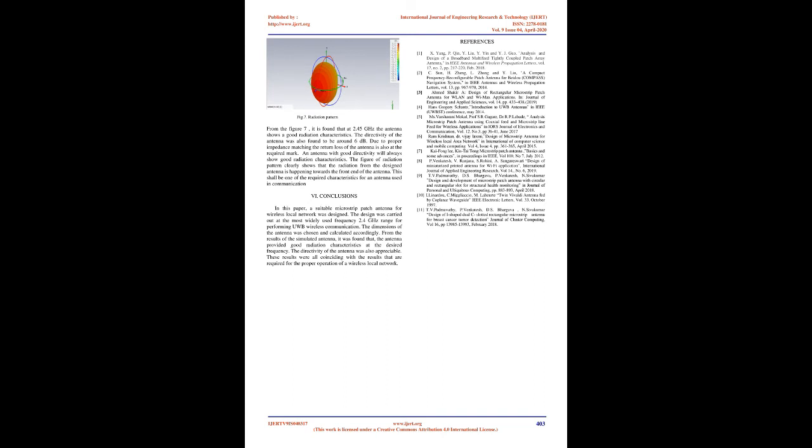A. Return loss. It is an important parameter that should be considered while designing an antenna. It measures the reflected energy due to impedance mismatch in an antenna system. For the antenna designed and simulated in this paper, the return loss was found to be -21 dB. Figure 4 is shown as follows. B. VSWR. It measures the minimum standing waves at the input port. The simulated figure 5 is shown as follows.